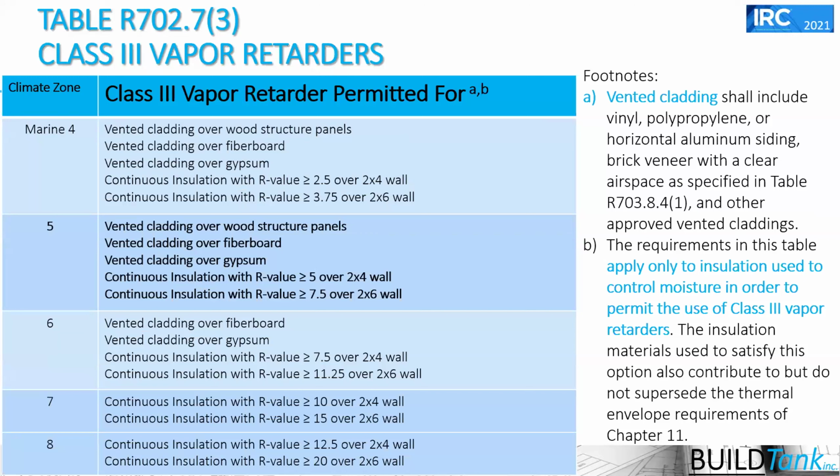So I've reduced the potential for condensation in the cavity, but I know that maybe some moisture might diffuse through a class 3 vapor retarder. I give that moisture the ability to dry back out seasonally in that assembly, and I have a more robust, more resilient, better insulated, better protected assembly from a moisture perspective as well. And I get a holistic assembly that's going to perform for me over time, which is ultimately what I want here.